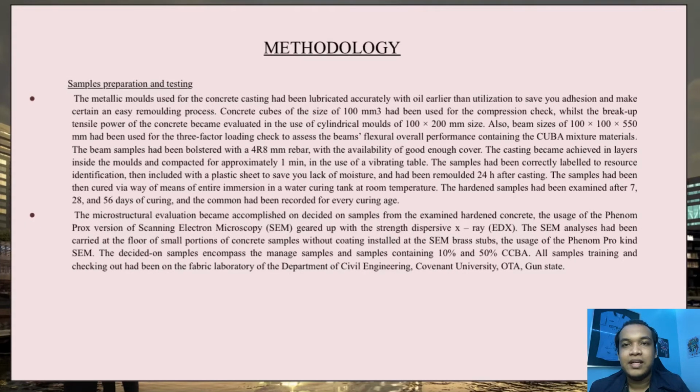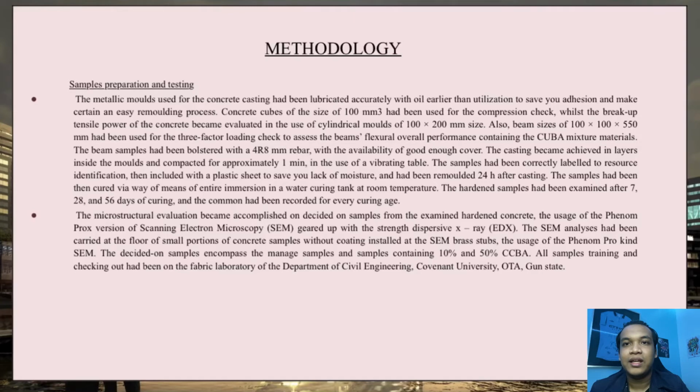The samples were then cured by complete immersion in a water curing tank at room temperature. The hardened samples were tested after 7, 28, and 56 days of curing, and the results were recorded for each curing age.